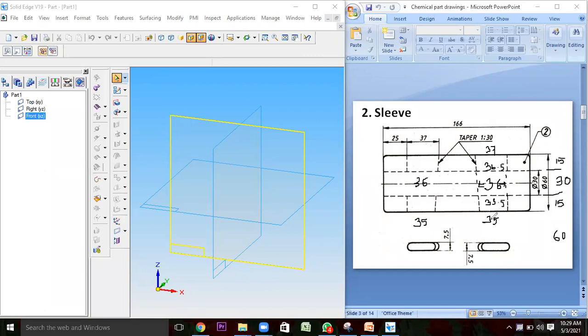So if I go from this bottom end to upper end, then this will be increasing by 1 mm, 35, then it will become for 30 mm travel 36, and for another 30 mm travel it will become 37, and for every interval of 15 mm, half of that 1 mm will be increased. Like from here to here it will be 35.5, and from here to here it will be 36 mm, and from here to here it will be 36.5 mm, and from here to here once again 0.5 mm will be increased, as vertically we are moving 15 mm.